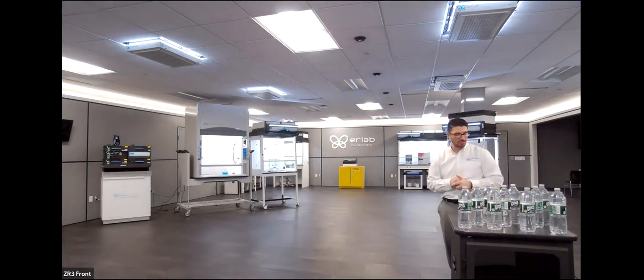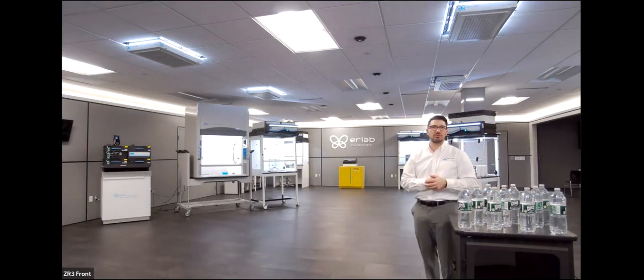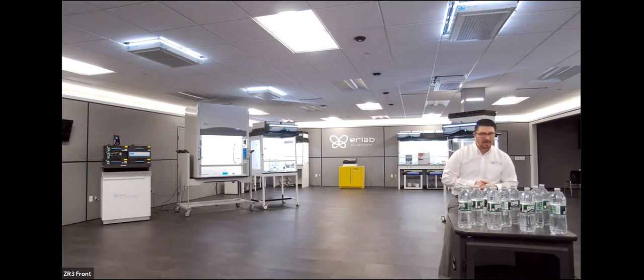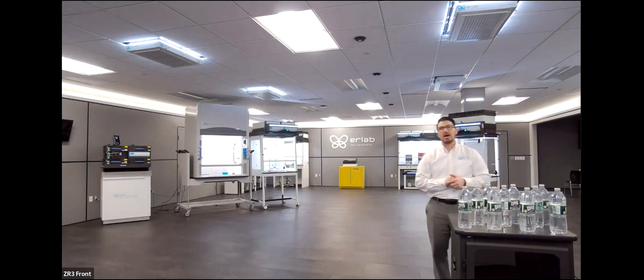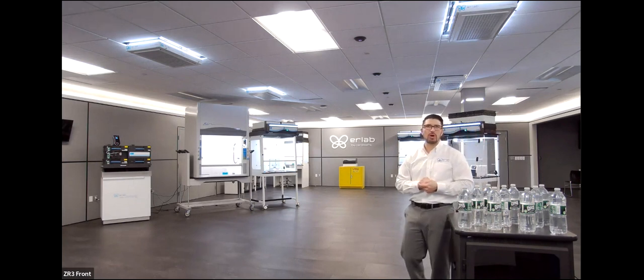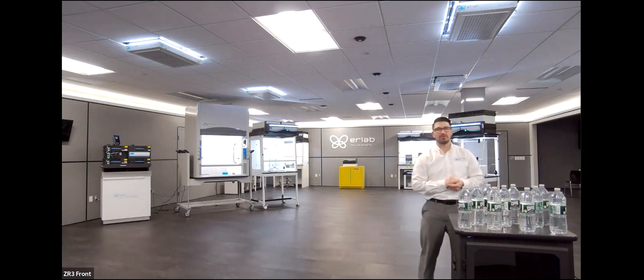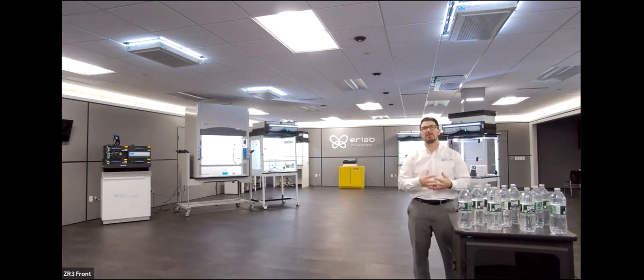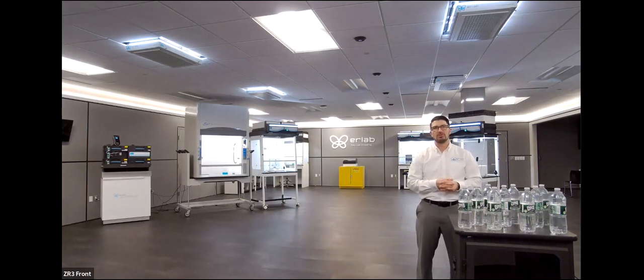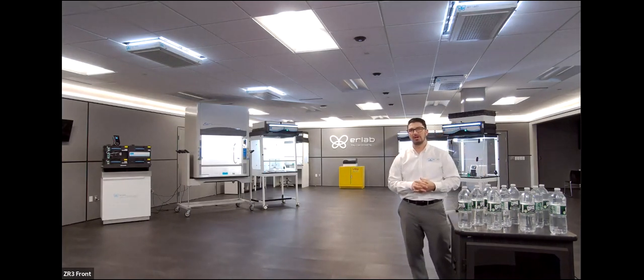I do got a question. So what is the average volume of air that the Halo will treat? So on average, it's one Halo every 10,000 cubic feet, which will add an additional 1 air exchange rate per hour. So again, we go out, we do site assessments, and it's going to depend on a number of different factors.